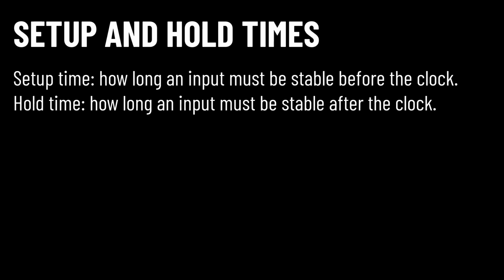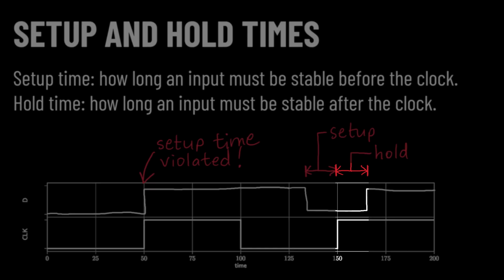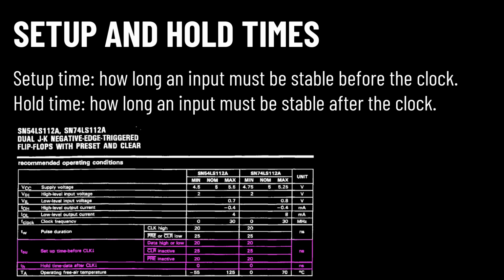Two other timing issues that have been previously discussed in this class are setup time and hold time. As a review, setup time is the length of time a signal needs to be stabilized on the input of a flip-flop prior to a triggering clock edge. Hold time is the length of time a signal needs to be stabilized on the input of a flip-flop after the triggering clock edge. These two values can be determined by reading a flip-flop datasheet.